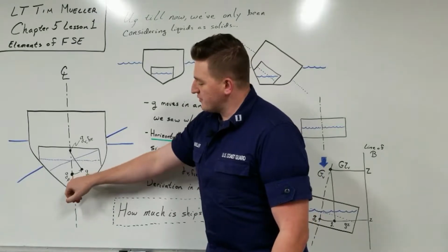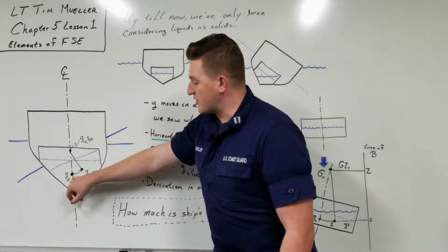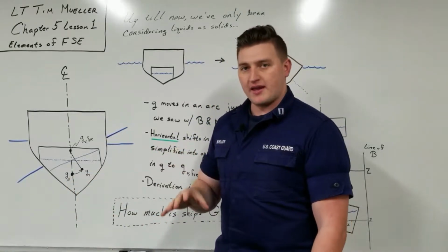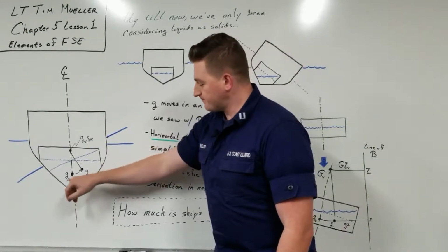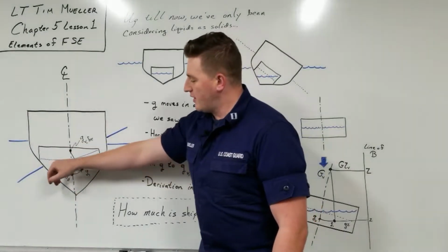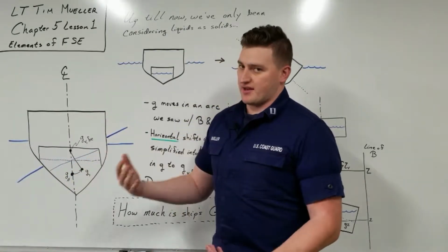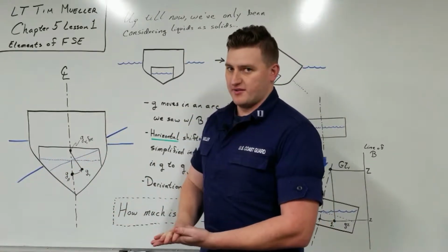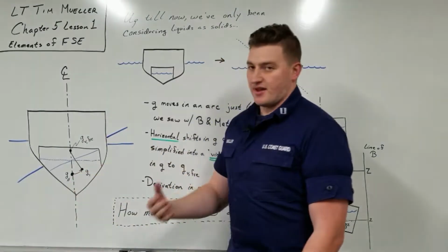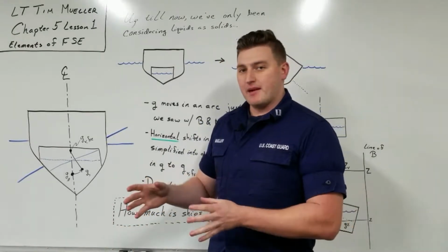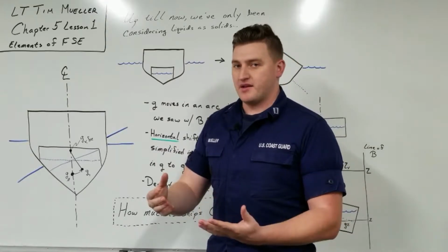So we have the original center of gravity of that water inside the tank at this location here, we're going to call lowercase g naught. So at lowercase g naught, or small g naught, when we incline over a little bit, we lose a triangle over here, but we gain that triangle over here, just like I mentioned in Chapter 0, Lesson 2 with the center of buoyancy. So it's going to swing in an arc, just like we saw with the center of buoyancy. And if you remember, the center of that arc, or the center of that whole circle around, was the metacenter.